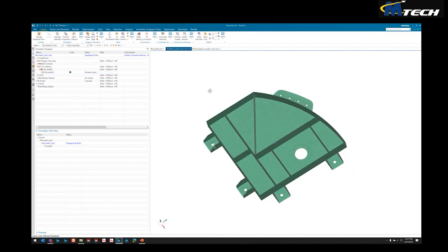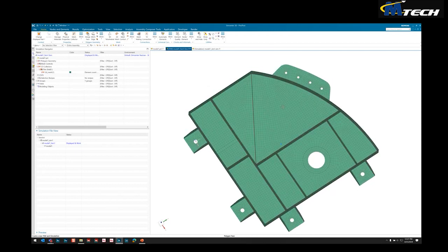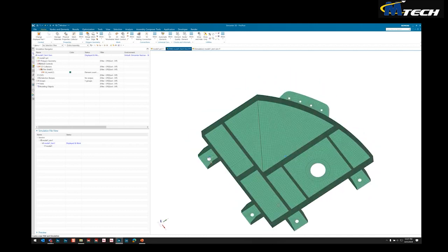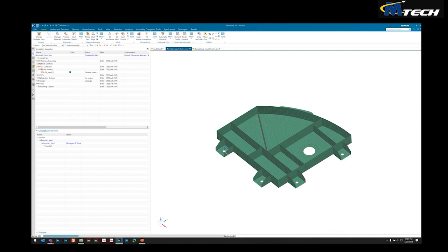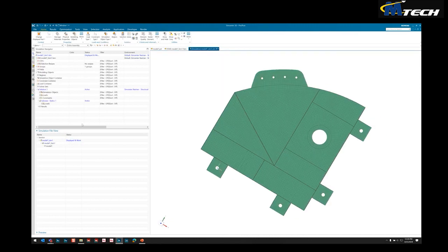All right. So now we've created our finite elements, our nodes, applied our material, and our thickness is now tied to our mid surface. And that allows us to change all of our element thicknesses by changing the face offset of the solid. Okay. So we'll go ahead and save this. Next, we'll go to our FEM or our SIM file.